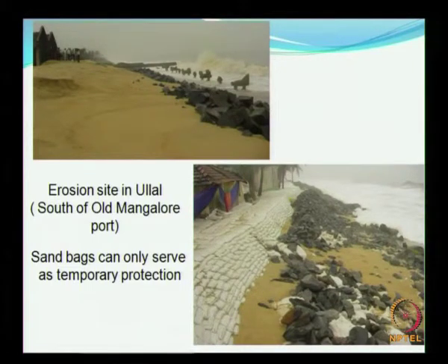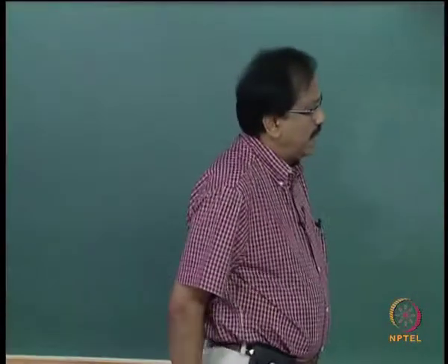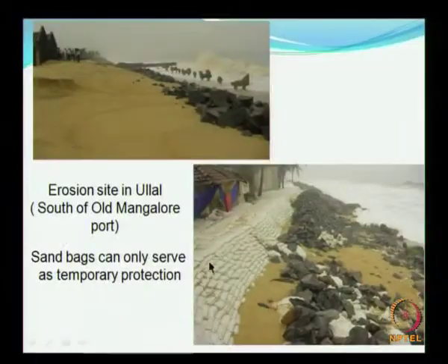So, this is in old Mangalore. This is a bit of an old picture. Now, the scenario may be quite different, but anyway I am using this picture to show you that geobags were also adopted, but failed miserably. This is somewhere in Ullal where you see the geobags filled, and they did not sustain the severe erosion that took place after the construction of the sea wall with geobags. Okay.